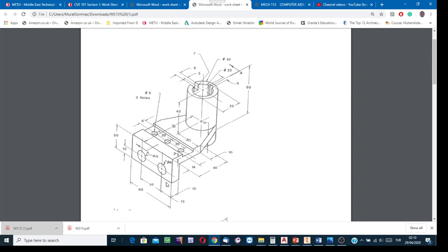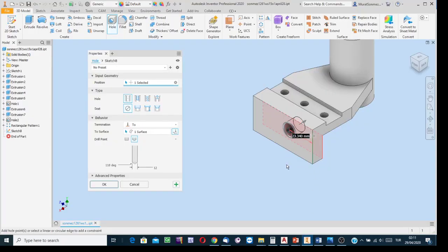And relative to the bottom edge, this boundary, it is 10. Indicate the location dimensions. Here it is 15, and indicate that edge, it is 10. And then say To, or first say To this surface and then input the coordinate values. The order is not so important.